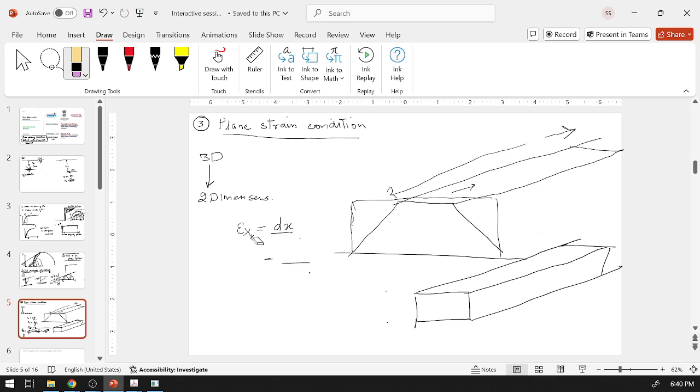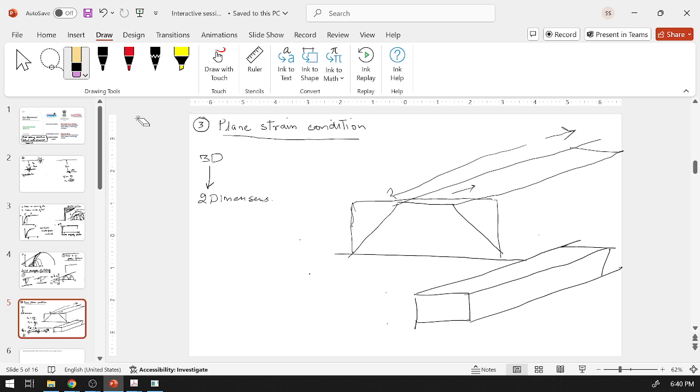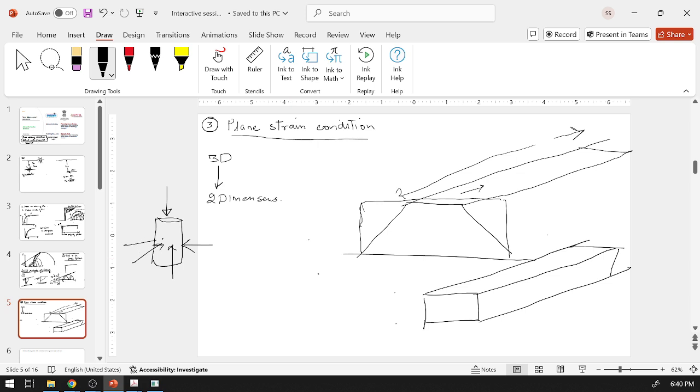I should have mentioned earlier that in any problem, for example, when you are taking the triaxial sample, you are taking the vertical direction and the horizontal direction, and you are assuming that the intermediate stresses are equal to the horizontal direction. Even in your direct shear test, you are taking the cross section, isn't it? So you are taking the vertical direction and you are shearing in this direction. You are not considering the third direction.